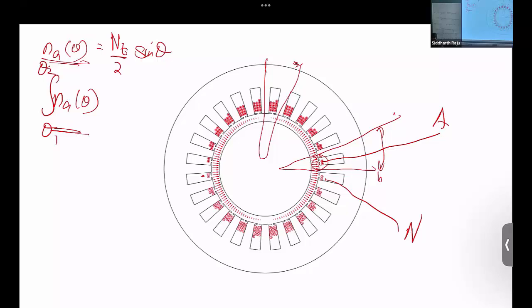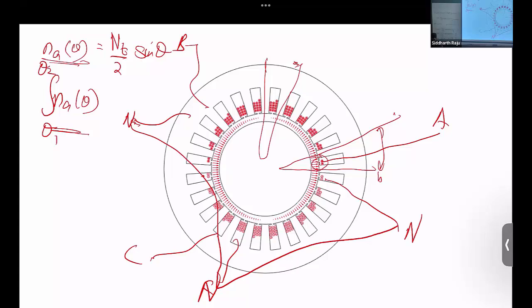So if you connect all the neutrals, you'll have A phase, and then similarly some terminal for B phase and its own return neutral, and then C phase and its own return neutral. All these neutrals will be tied together, because the sum of the three currents has to be zero in the balanced case. So why even bring the terminal out? The motor manufacturer will just wind all of these, connect all the neutrals together and bury it in the motor. You won't typically get it out. Some motors do bring those out. If you request it, they will be able to bring that out as well if you need it. Okay.